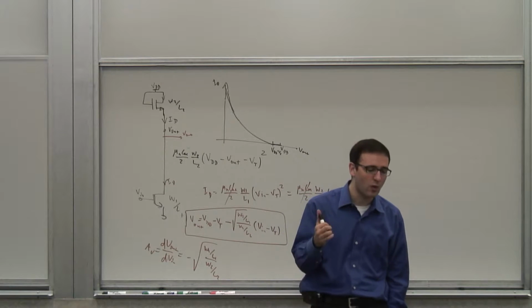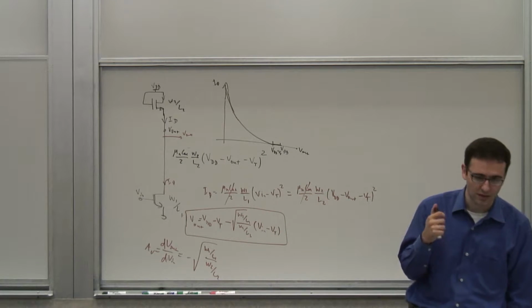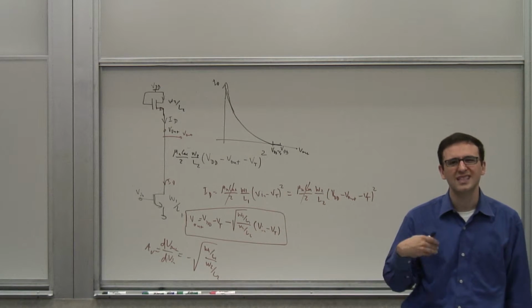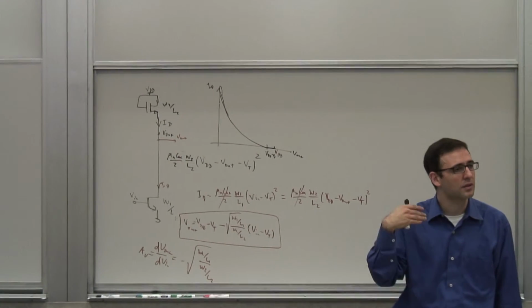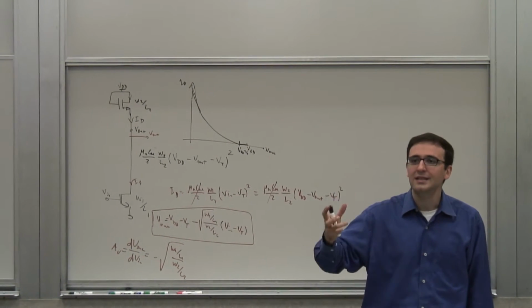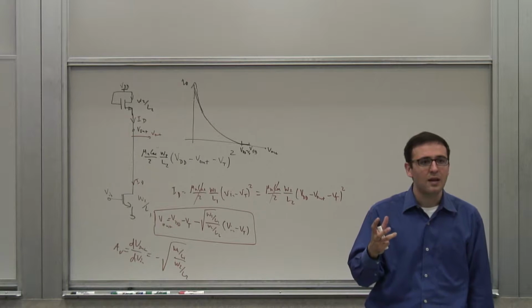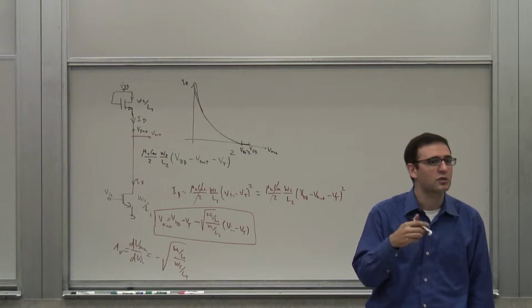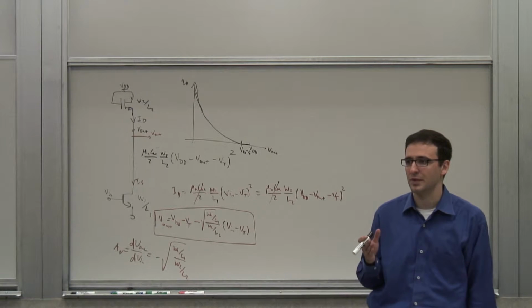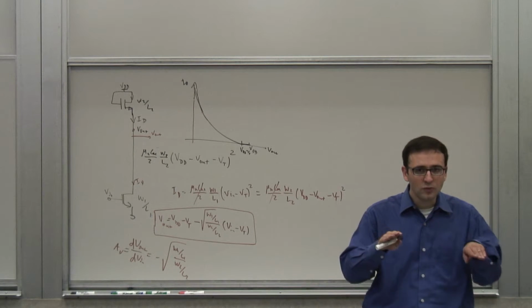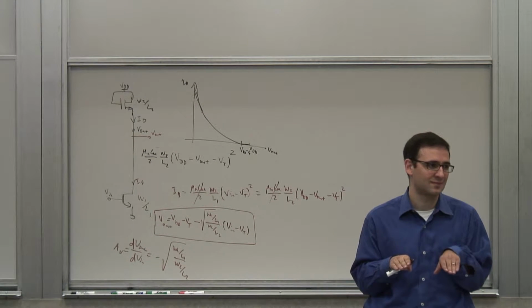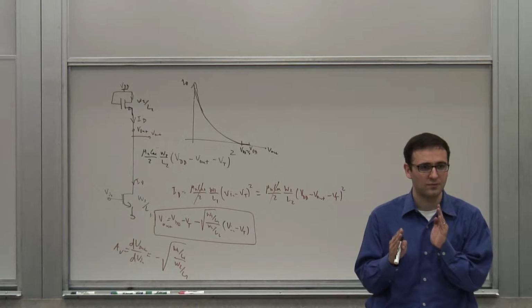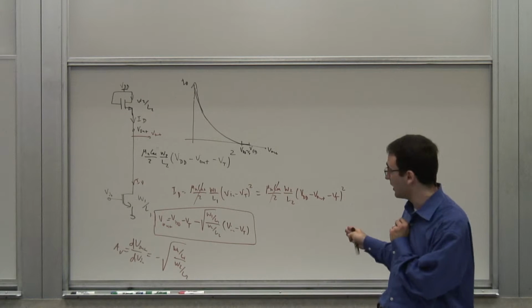And this is the way you want your circuits to be in a lot of integrated circuits. We'll see this as a recurrent theme, that you ideally want the gain and some of the important parameters in your circuit to depend on ratios of things that move together, as opposed to absolute values. So from that perspective, this is a good thing.